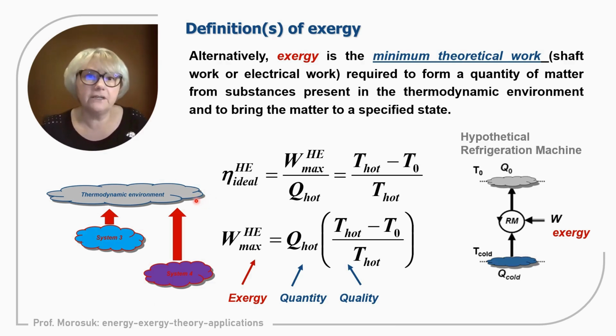Then we have an alternative definition: exergy is the minimum theoretical work required to supply to the system to bring the system to full equilibrium with the thermodynamic environment, but from the lower temperature level to the higher. The equations will be absolutely the same as for the previous case, but now please follow all the adjustments that should be done in these equations.